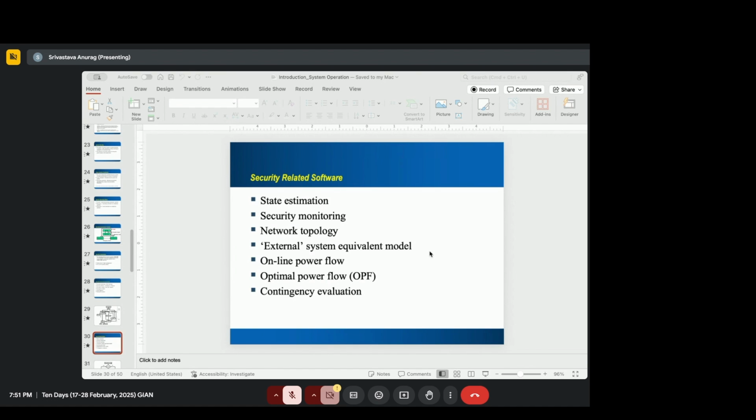And that's what we went with. Most of the existing field analysis keeps it separate, because if you want to integrate them and make the PMU a part of SCADA, it requires us to increase the speed of SCADA measurement, which is possible because it is being measured, but the communication link and all the servers, or all the data collection points, need more powerful storage and processing to make it happen, which again requires a lot of money.